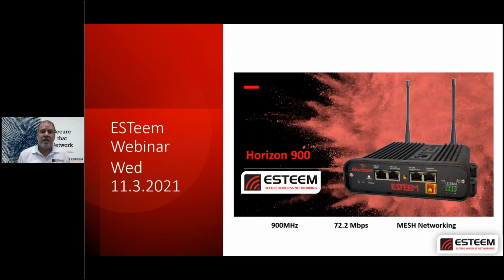So we did it. We built you a 900 megahertz radio that can mesh, that gives us up to 72 megabits of RF data rate. That still takes advantage of that 900 megahertz, so we get a little bit better distance, and a little bit of penetration into some of those nastier environments. So hope you can join us in a couple of weeks.